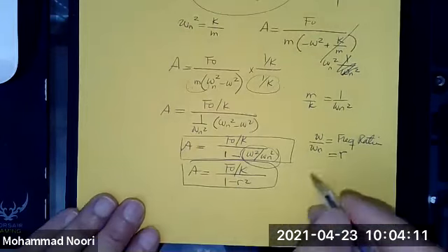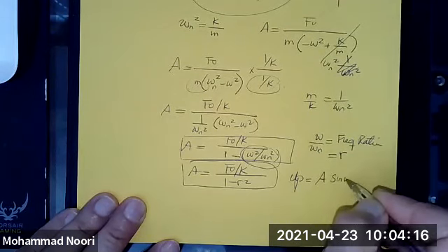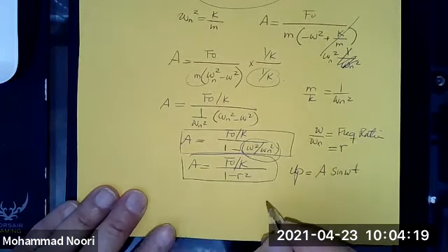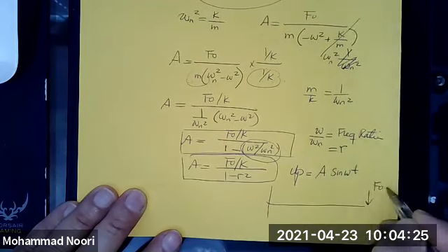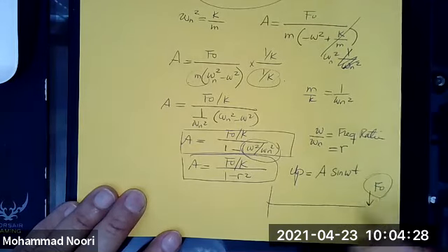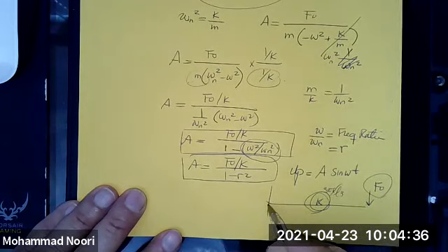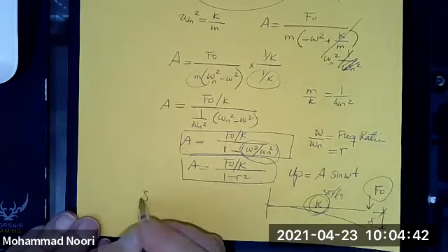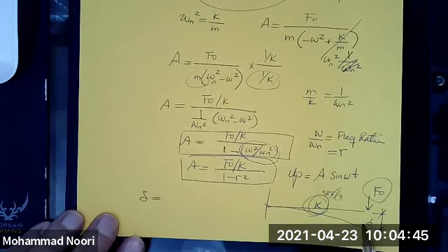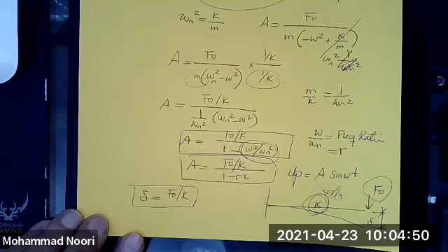But what I want you to think about is this. I'm going to discuss it next time, of course, right? If you have, let's say, a system subjected to a constant load of magnitude F naught, and this has a stiffness, it's a beam, so it would be 3EI over L cubed, but I don't care about that, just the stiffness. So how much is this beam going to displace? Delta. What is delta? Static displacement. Just say spring, right? So that would be F0 over k, right?